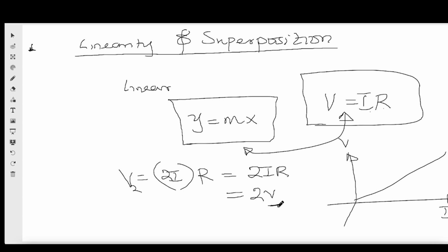So basically, let's go into the superposition principle and see how it is applied to circuits. Remember, I was saying that the principle is only applied to a linear circuit with more than one independent source. And what is done when we have more than one independent source? We can break the circuit into independent circuits having just one source.